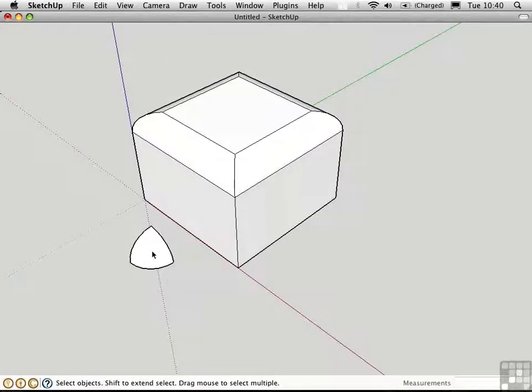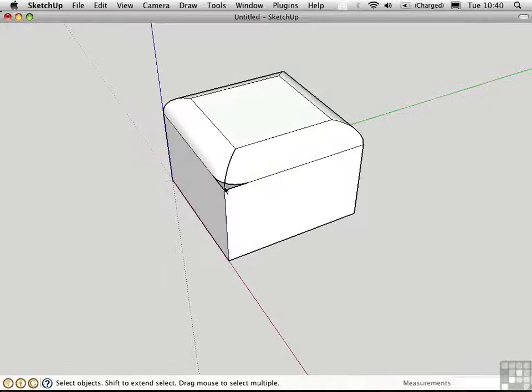Triple click on the eighth of a sphere to select the faces and its edges. Move it from this upper corner point and place it right where it belongs, right here. Deselect, and then delete these extraneous surfaces that have been cut by that eighth of a sphere. You also need to delete this edge, which is just floating out in space. And you can see that because it's bold. It means it's a profile edge.